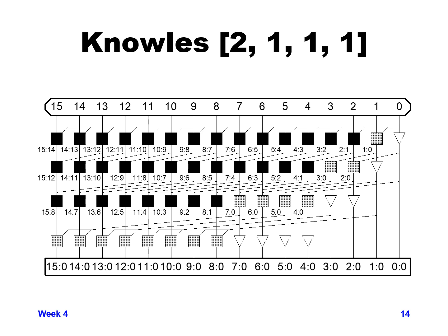It's less than that, but it doesn't have the maximum fan out that the Kogge-Stone design had as well. So it's balancing between those 2. So in this case, we're balancing between the Sklansky design and the Kogge-Stone design, where we might have a little bit more in terms of wire tracks versus fan out, but we have the minimum amount of logic levels. So we're not balancing off logic levels, we're balancing off fan out versus wire tracks.